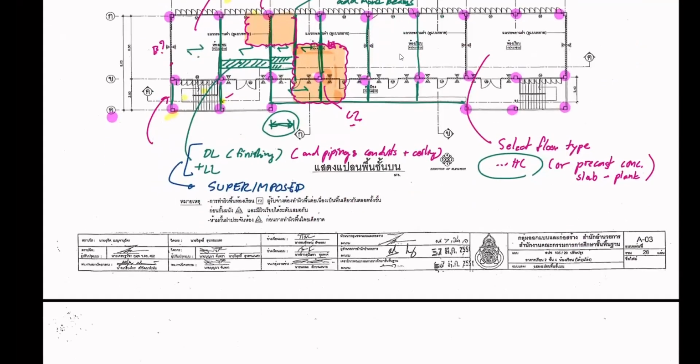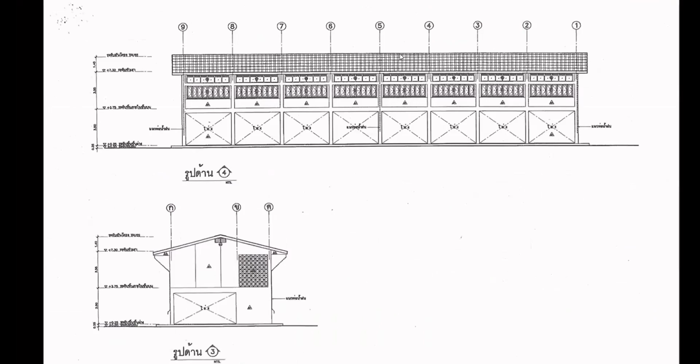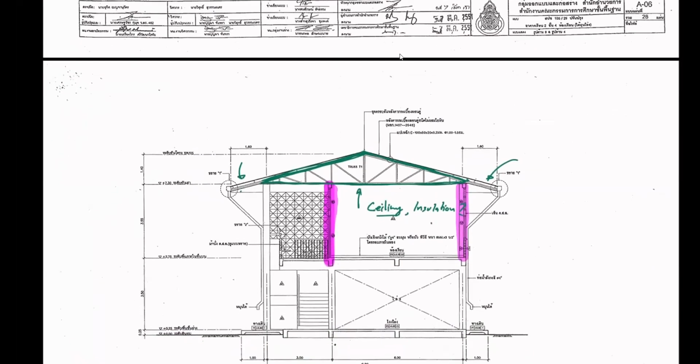And perhaps you can use this information to figure out the depth of the truss. See, it's also given here. That's the depth available to you. And I'd say this is a pretty small truss, 6 meters in midspan and 9 meters cantilever. So it should be okay, and the load is pretty light. Keep in mind that this cantilever is pretty large, so the force in the members here might be dominant.